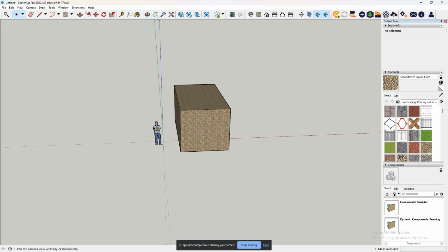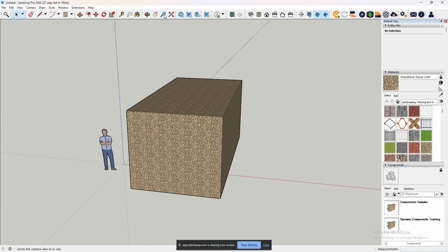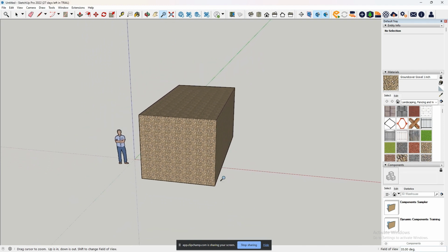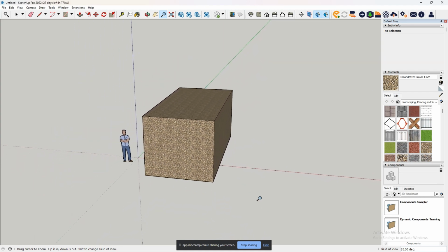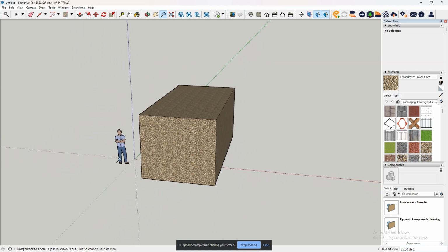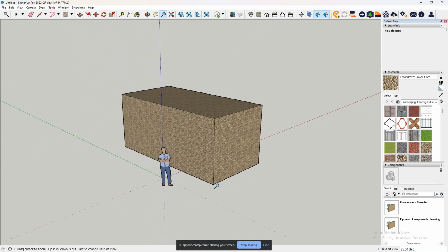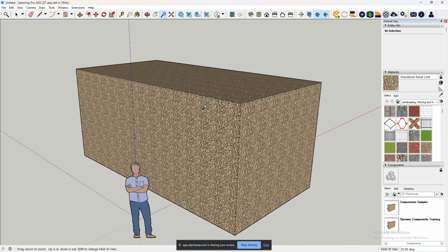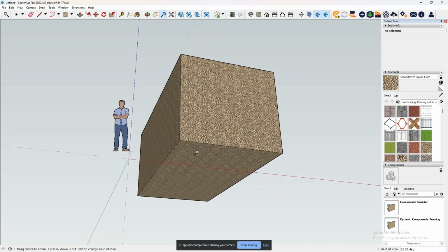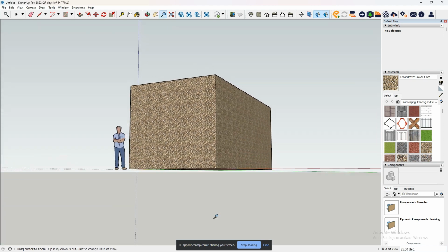Besides the orbit and hand tool, which we've already touched on, then you have these two zoom tools here, which obviously if you click on the magnifying glass for the first zoom and just hold it down, as you could imagine, it zooms in and out of your screen, and if you use this in conjunction with the orbit tool, as I said, bound to your mouse, you can get some good angles of your model.